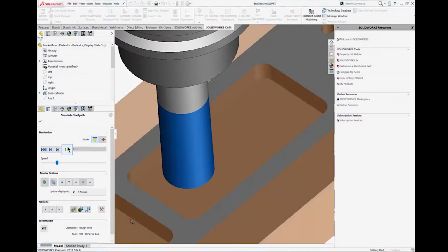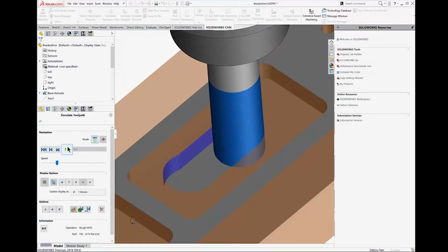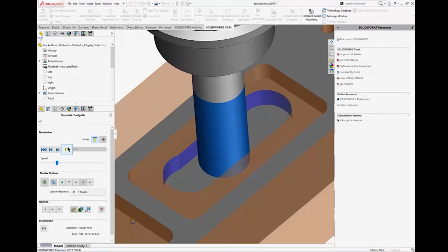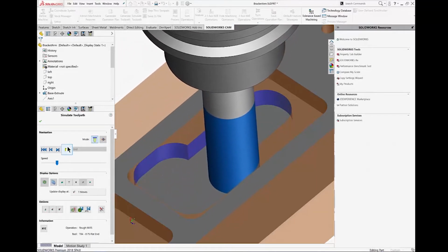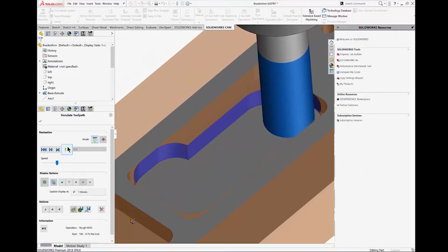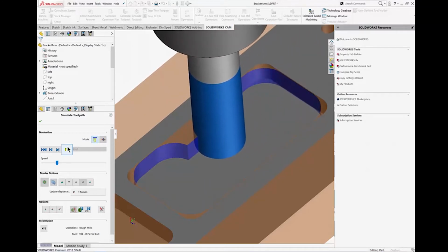Now, let's talk about milling. There are 3 improvements in particular that I want to highlight, being the taper and neck option for tools, corner slowdown, and move feature. These aren't all the improvements in milling, so make sure you check out the What's New documentation for more information. A big issue with optimizing toolpath in SolidWorks CAM had been the corners. You could only run a single feed rate. The additional tool engagement would force you to run the tool slower for the entire cut, or you would need to get additional post edits or manually edit the code.